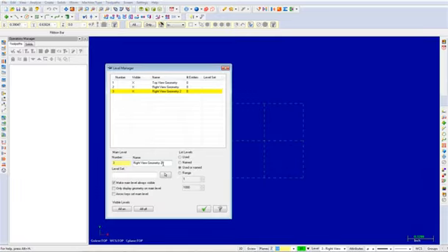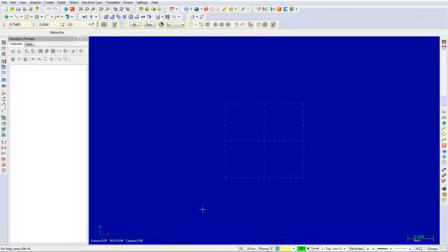Then select number 1 and choose the All Off button to make level 2 and level 3 invisible. Select the OK button to exit the Level Manager. To help differentiate between the geometry when the levels are active, we will use two different colors to create the geometry. Select the color button at the bottom of the screen and input the number of 10 if it's not already been set. Then choose the OK button.